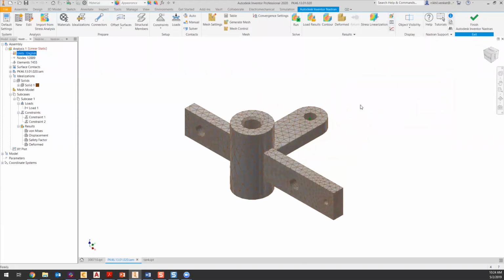Yep. And if you had a percentage where the absolute value was less, it would take longer for the mesh to converge. Yeah. And also, if you had a larger number of iterations, it'll just keep going. So like I said before, don't make that number too big, at least on the first try, because we kind of have an idea. It's like, okay, the mesh needs to be refined in these areas. Maybe after this trial, we can manually refine the mesh in those areas, or run it again with some more critical numbers in there. Obviously not changing it too much.